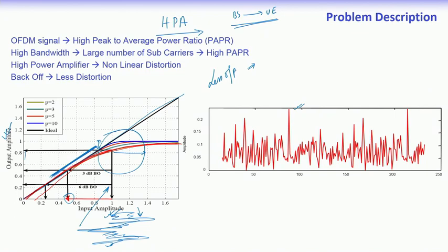So, once it impacts the frequency domain shape, it causes a lot of in-band distortion. A lot of in-band distortion ultimately results in a poor signal to interference plus noise ratio at the receiver side. Graphically, this overlaid blue colored picture shows the signal that comes out. Obviously, the spectrum characteristics of this signal are different from what is originally present in the red colored signal.